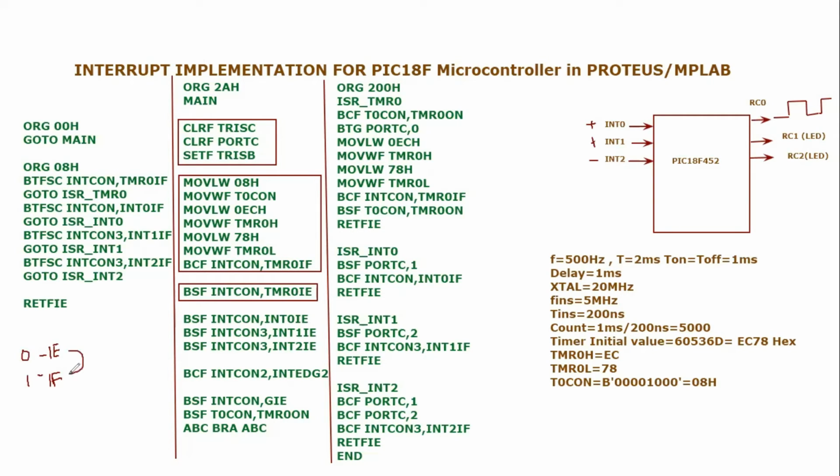And then both of these inputs are passed through an AND gate, and the output goes to the main interrupt output, right? But you know that if we have not made this individual enable equal to 1, then even if we have the interrupt flag high, it won't proceed to the output. So what we have to do is also make it 1, right? Initially it is 0 and we have to make it 1, and that's what we are doing in this specific line. We are actually enabling the interrupt enable of timer 0, and then the next 3 lines are dedicated for interrupt